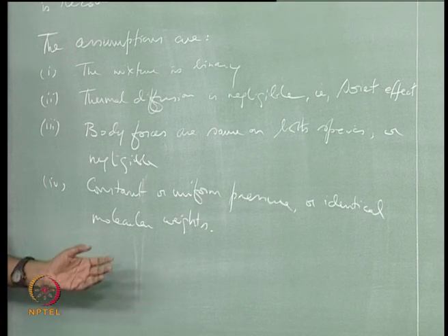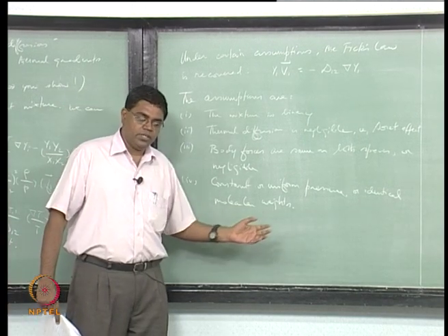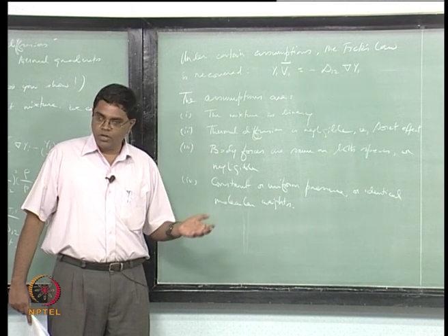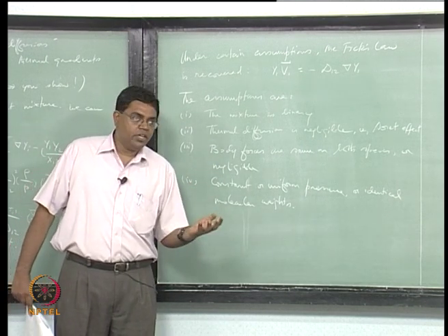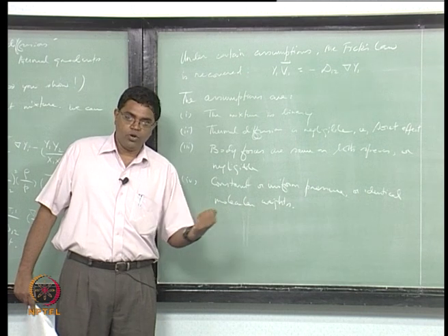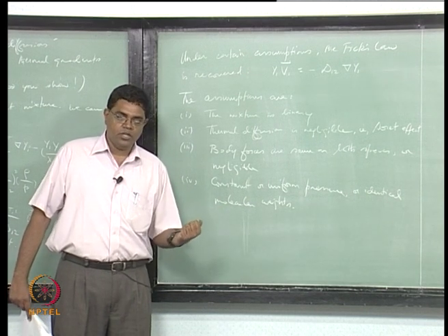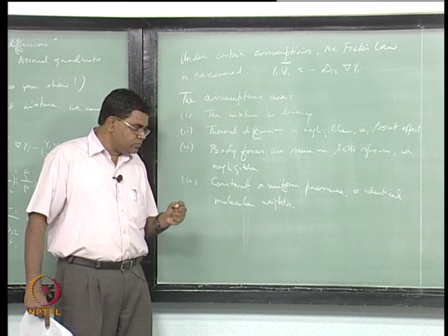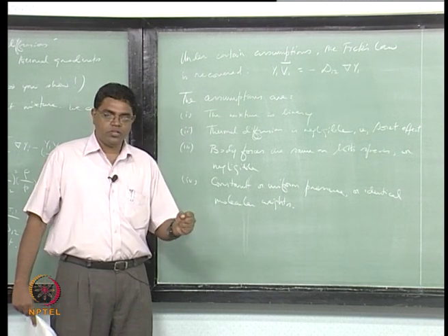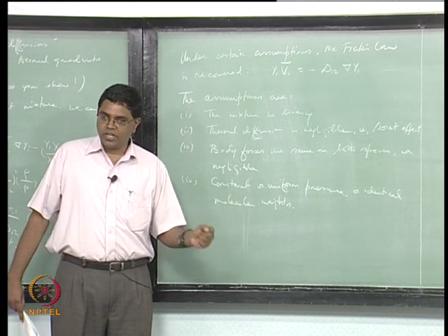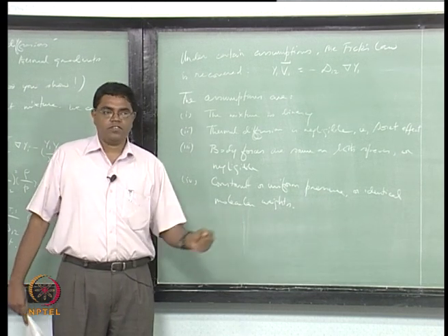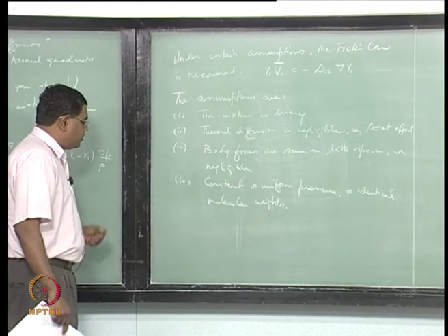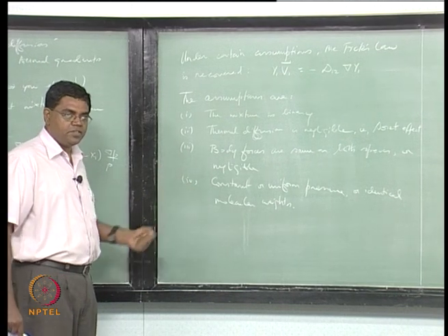For example, in propulsion, the specific impulse goes as the square root of T divided by molecular weight, and it's in the denominator. So if you have a small change in the molecular weight, say from 30 to 20 or 28 to 18, it makes a significant difference in your Isp calculations, and people die for getting that kind of increase in Isp.